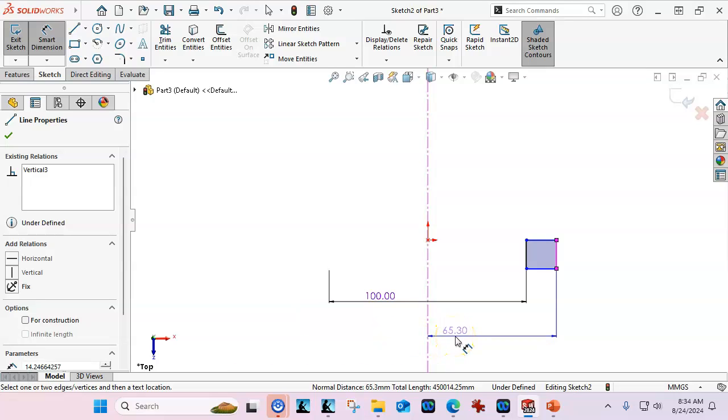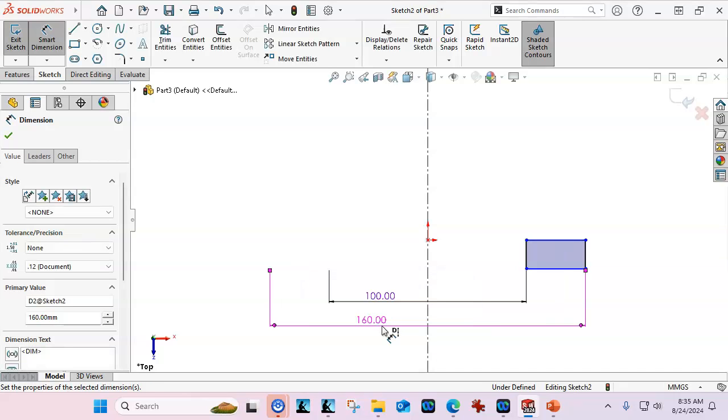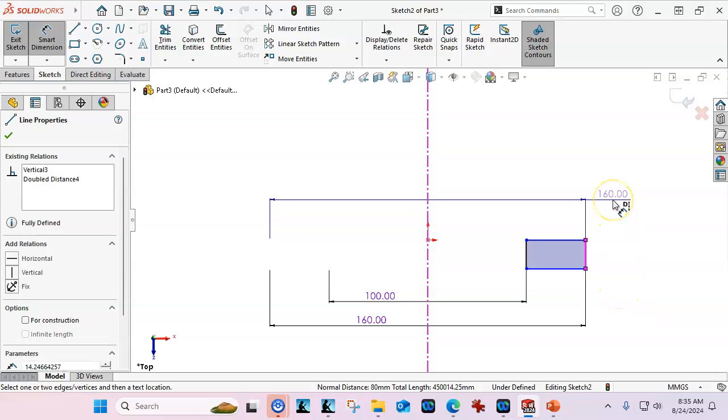Oh, and because it's a revolve, something that I do naturally is make sure that if you want the diametral dimension, you are on the opposite side of the center line. If I'd drawn my rectangle over here, I would be dragging it over here. So in between the object and the center line is radial. To the opposite side of the center line gives you a diametral. So 160 and a thickness, and it still thinks it's in diameter.